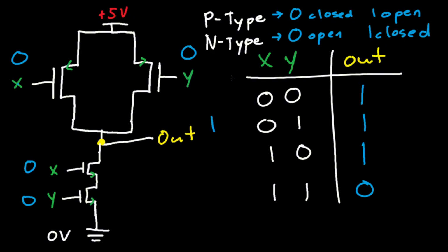So remember, our logics are 0 and 0 for X, Y. Therefore, the input logics are 0, 0 for X, Y down on these two transistors. Well, if you have 0, 0 as the inputs for these N-type transistors, then you have open switches. If you have open switches, that means current can't go here. Let's draw this.